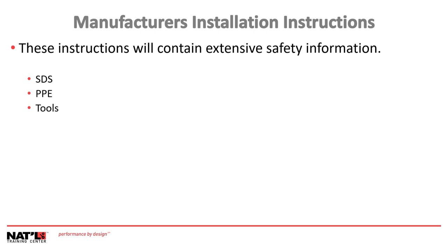Use a flashlight or permanent lights only. Do not smoke or create sparks when working on batteries. Never lay metal tools such as wrenches or other material on top of the batteries. Insulate tool handles or preferably use insulated tools to protect against shorting.